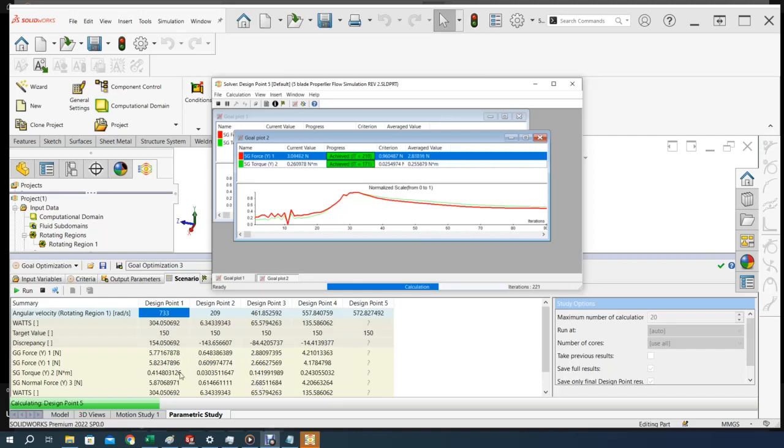And I'm measuring the torque, which makes sense. At the highest RPM, I got the highest torque, and so forth, but it drops. And here you can see the watts at the different RPMs, about 135 at 557, but now it is doing an iteration at 572, and might be this one. I think this is about to finish after 2 hours. We let it go a little bit further, and I'll be back when this is done.